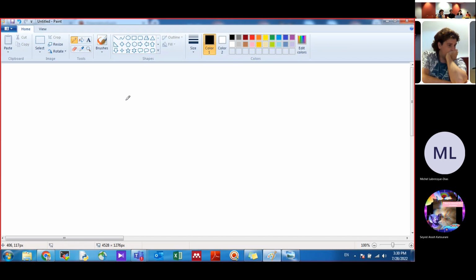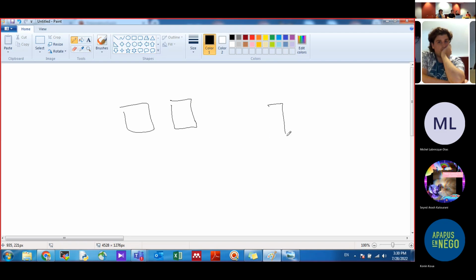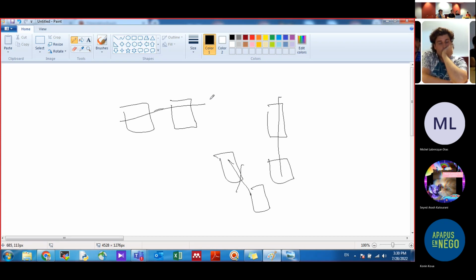The first one, when you're going to lay out a differential pair, is to lay it out horizontal or vertical. It shouldn't be like this, because electrons move like that. So it shouldn't be something like this. This is not correct. It should be like this or like this. This is very important for differential pairs.